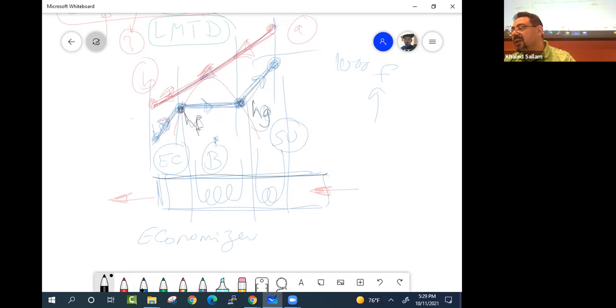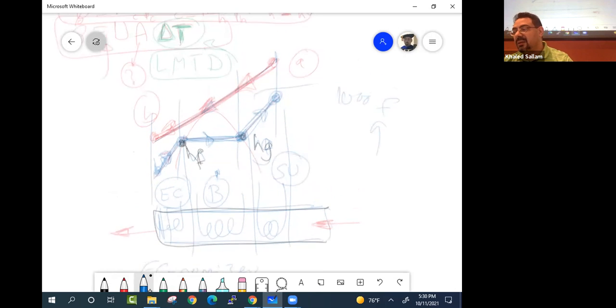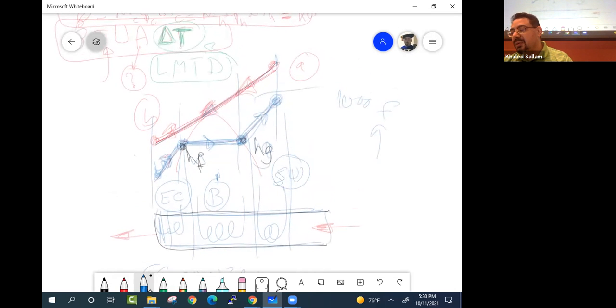So this is really kind of a boiler. We are basically designing 3 coils for the boiler. Yes. Just to clarify what they're called, you've got the superheater, the boiler, and the economizer. Economizer, coming from economy. Yep. Nobel Prize in economy, right? So the superheater, the boiler, and the economizer.